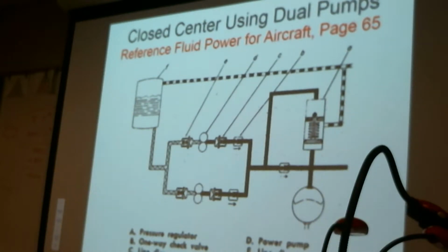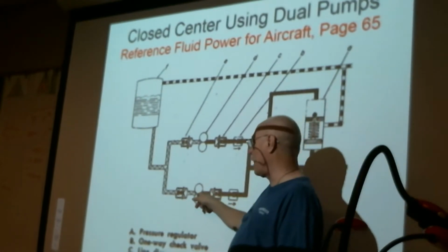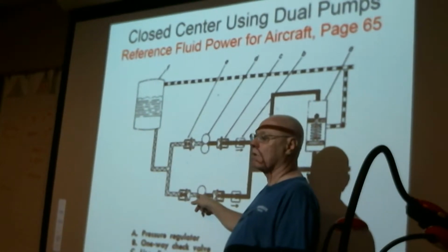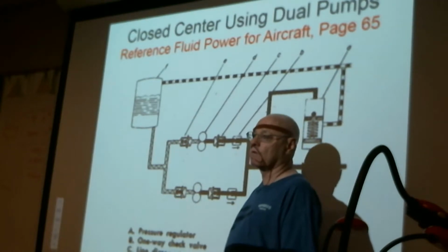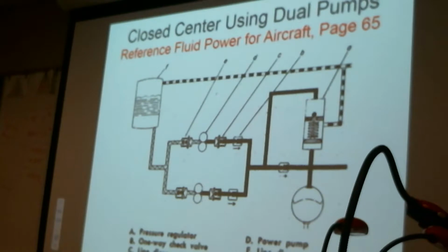There's something that's kind of true too. Fluid takes the path of least resistance, like water. So rather than the fluid trying to anchor into the accumulator, the fluid flow would try to run backwards through a pump that's being motored, may even go back to the reservoir. So it prevents motoring in an inoperative pump. That's why we have it.